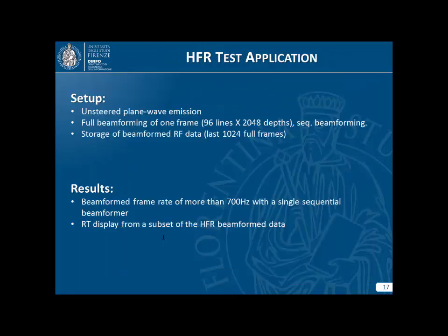And now I show you the results on the use of the full system. And we show here a simple high frame rate application. The setup was to fire one unsteered plane wave. And the system has been configured to make one full frame beamforming for each transmitted plane wave. And also the system is configured to store up to 1,000 full beamformed frames.